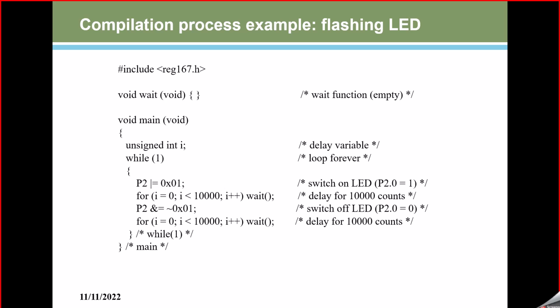So the statement P2 is equal to R is equal to, this is an OR operation, which is doing the OR operation with the data 0x01. So it is trying to switch on the LED of the P2.0 pin, that is, making it 1. We are just trying to toggle or switch on the port pin, correct? This is the hardware programming part. Generally, it looks like we are trying to write a program for the microcontroller hardware. That's why we call embedded C a hardware oriented programming language.